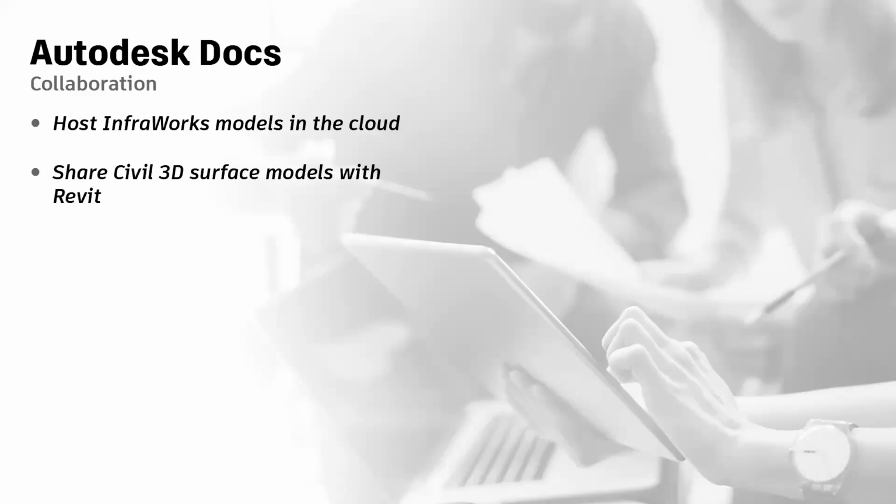I can also use Docs as a conduit to share Civil 3D surfaces with Revit. If you've ever tried sharing a Civil 3D surface with Revit, historically, that's been kind of a painful thing. Sometimes you may move it over, try and do it as a solid maybe, but then it doesn't act like a Revit surface. You can't move objects to the elevation. You can't create sections. It doesn't maintain the triangulation. Using Docs, I can create a link between that Civil 3D surface and Revit, and that surface will maintain full fidelity, same triangulation that it has in Civil 3D.